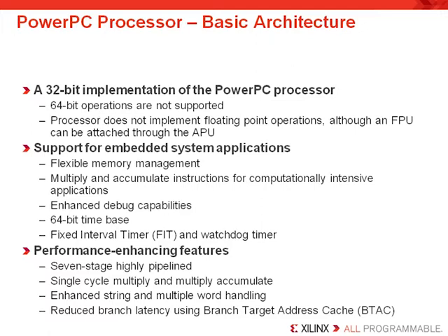Multiply and accumulate instructions for computationally intensive applications have also been enhanced. There's a 64-bit time base, there's the FIT timer and the watchdog timer as I mentioned, and of course this processor is a 7-stage highly pipelined processor, and it supports single cycle multiply and accumulate arithmetic functions.